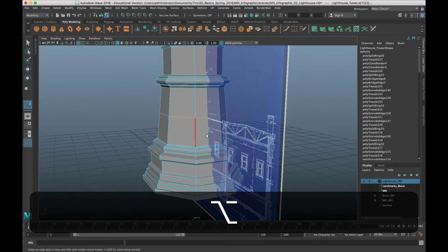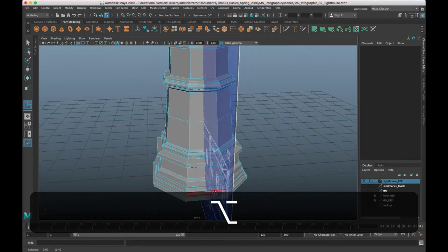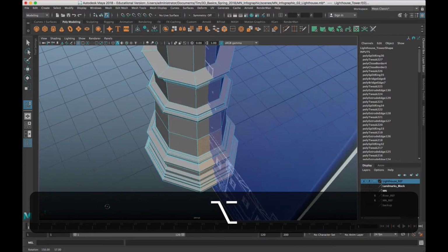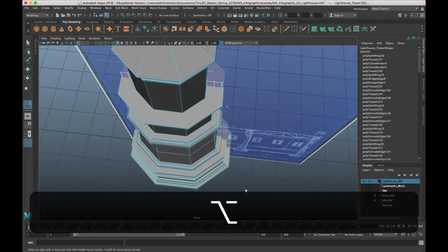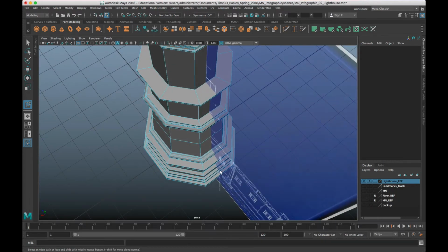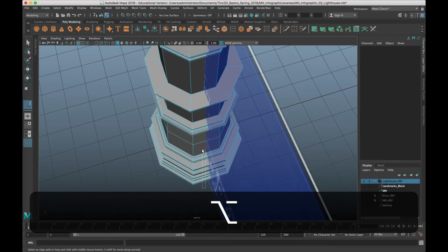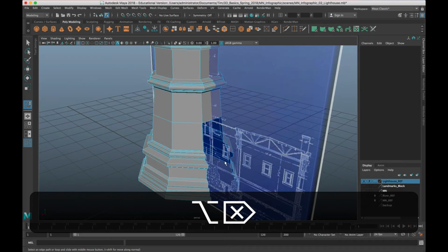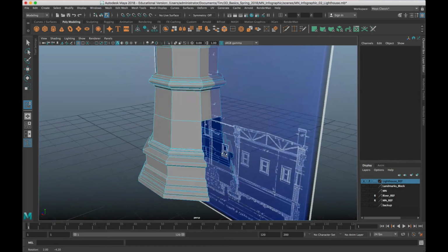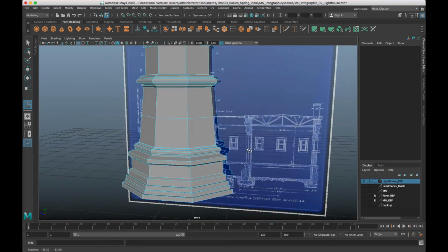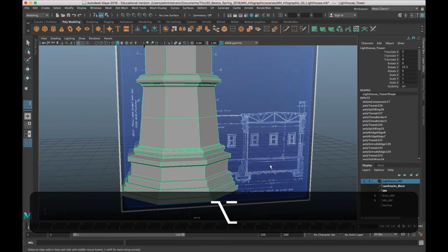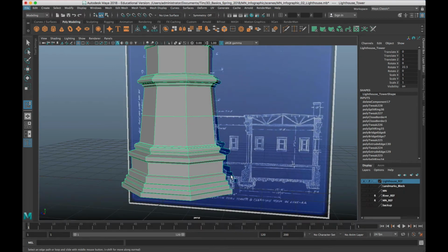Okay, so now that I have that defined, I'm going to face mode. I'm just going to click and drag, select all those faces. Oops. Let's make sure we're not selecting the other side. I'll rotate around a little bit so I don't select the faces I don't want to delete. There we go. So I just have that side and hit delete. Lovely, perfect, excellent, good. All right, so now that's defined, and I can move on to my annexed building.